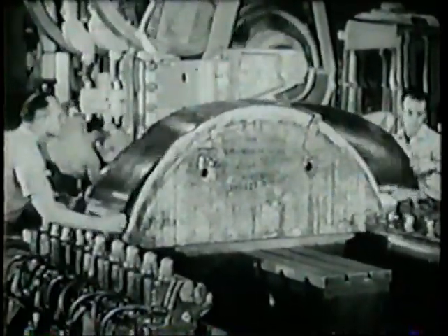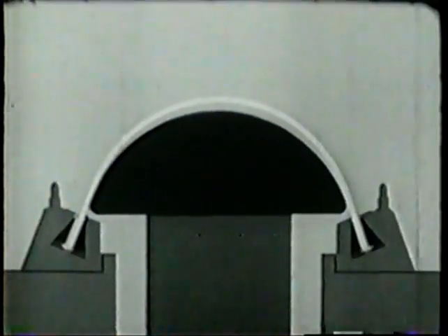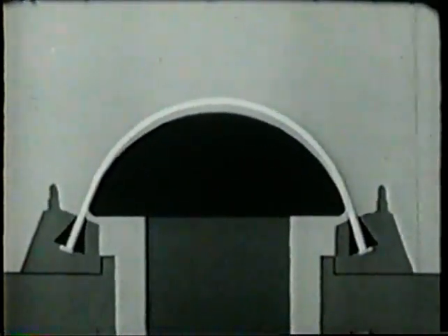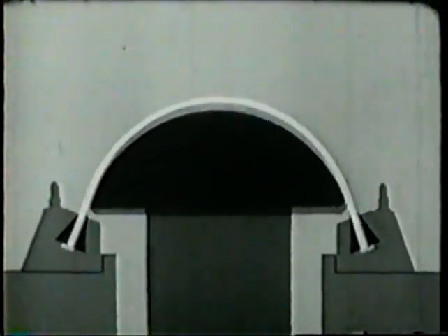Stretch press forming of aluminum alloy sheets is designed chiefly for the fabrication of parts with double curvatures. In stretch press forming, the opposite ends of a section of aluminum sheet are inserted into clamps. The die, located on a table midway between the clamps, moves upward, contacts the alloy sheet, and stretches it beyond the metal's elastic limit. The sheet is now plastically deformed to the shape of the die.